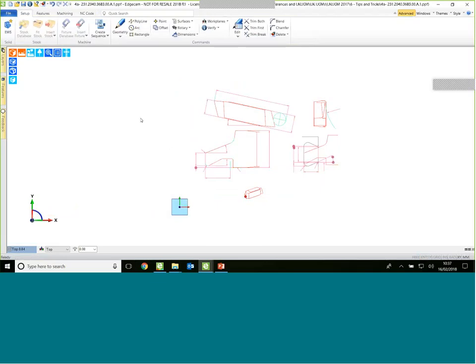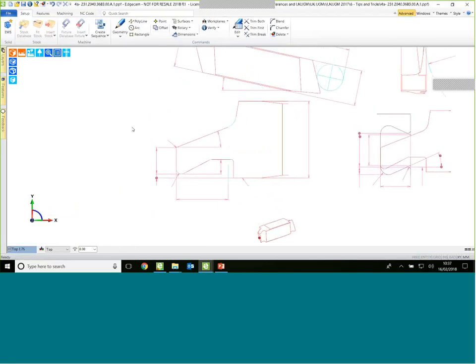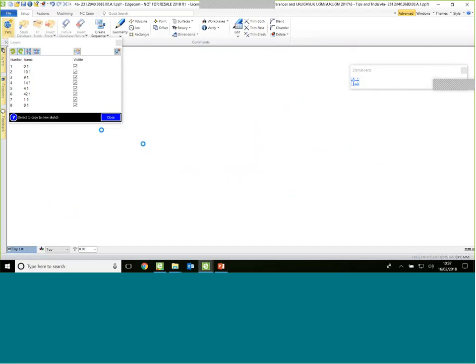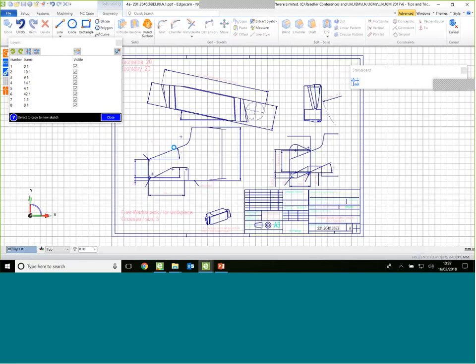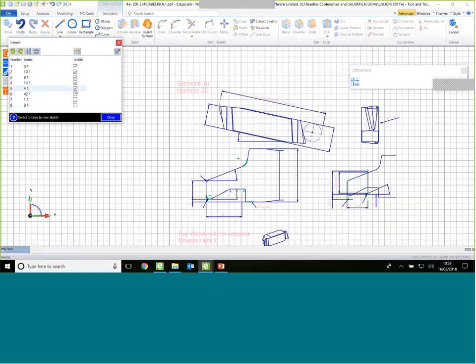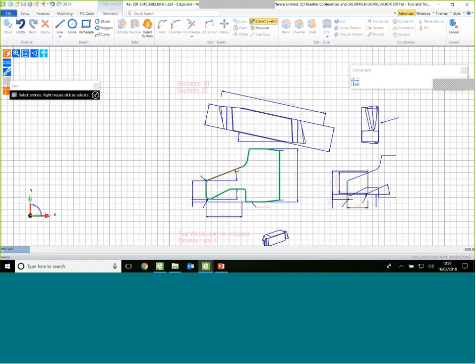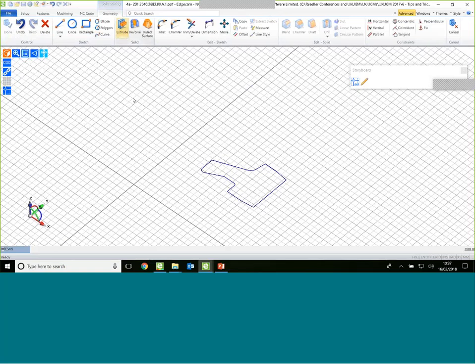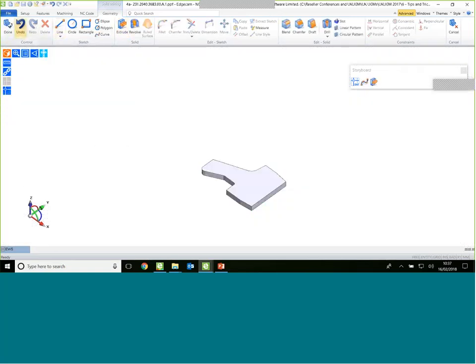There we go. So that's another way of cleaning the file up. So we're nearly down to the bit that we want to get down to. But you might also want to entertain the idea of using EWS. And what EWS will do for us is it will say, well, here's all your layers. So I can begin to separate the wheat from the chaff by using layers. Then I can ask EWS to extract the solid or extract the edges, which is this area here. And now it will selfishly only concentrate on that bit there. And I can go off and in this case do an extrusion command. And this was the bit that I was after in the first place.